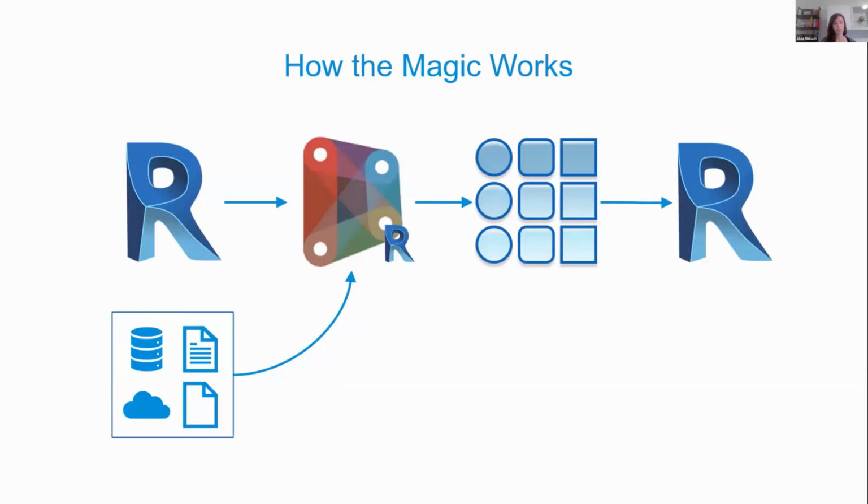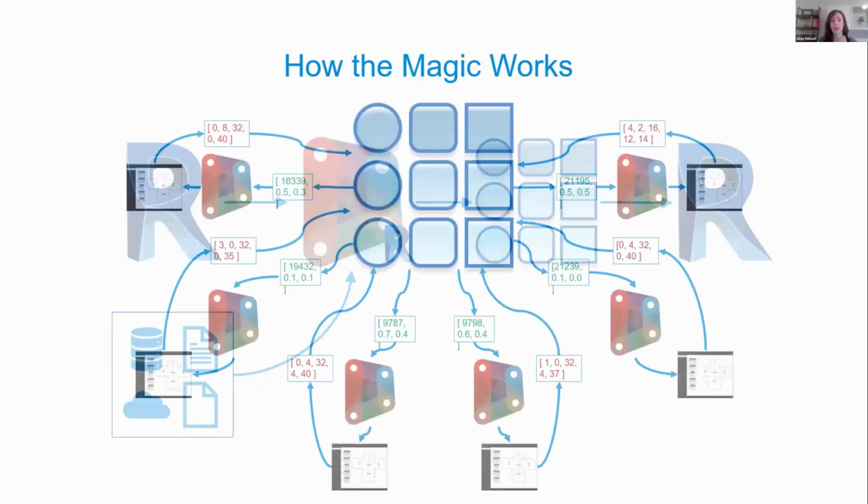So you can imagine the Revit data goes into Dynamo for Revit. The resulting graph is built and packed into a new Dynamo file, which is then sent to Generative Design, and then eventually is sent back into Revit. That's kind of just the typical workflow for Generative Design.